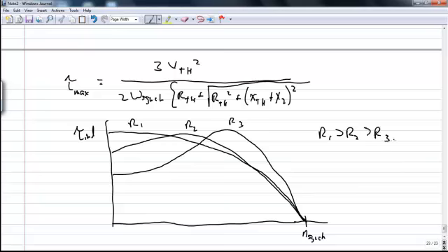So when I put more and more resistance into the rotor circuit, my starting torque goes up. Here's the point: when my speed is 0 with little resistance, my starting torque is here. As I add some resistance, it goes up, and if I add more resistance, it continues to go up. I can use this to create more torque at starting for a very heavy load.